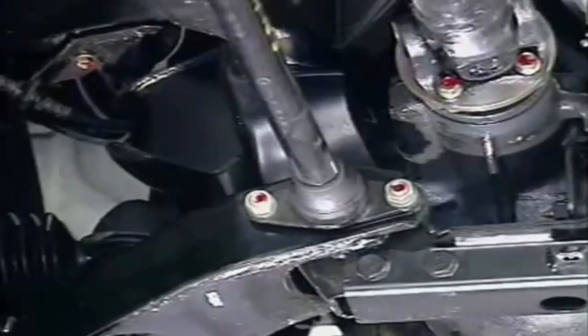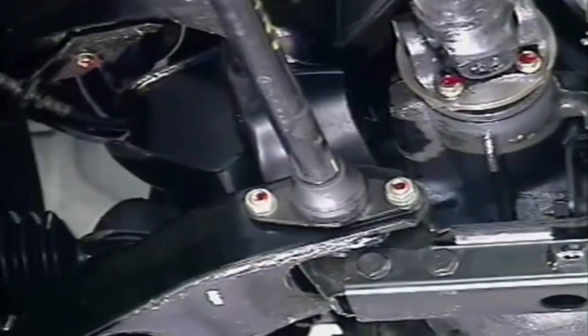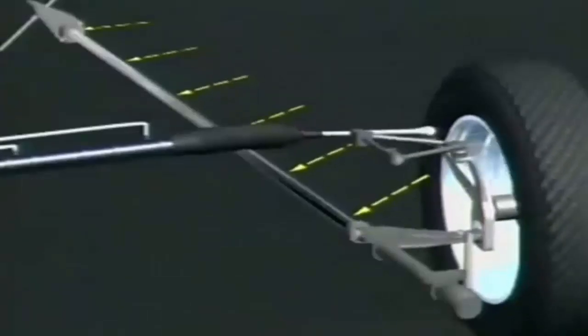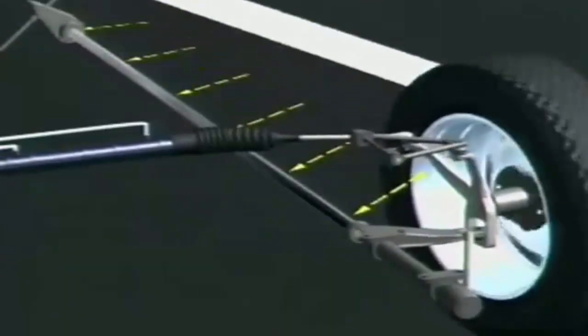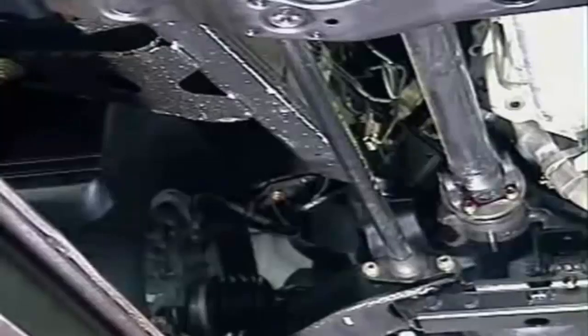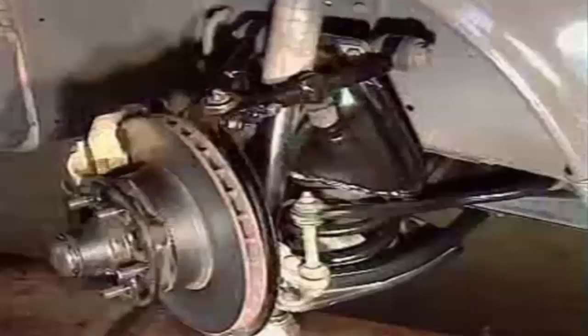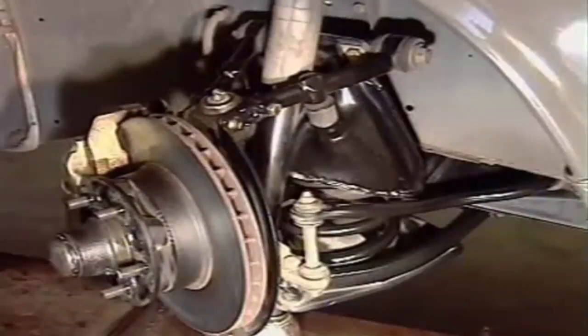The torsion bar is attached at the inner fulcrum point of the wishbone, or control arm. As the suspension is deflected, it twists around its center. It can be fitted to the upper or the lower link, depending on the type of vehicle. The upper link is shorter than the lower one, irrespective of the springing method used.